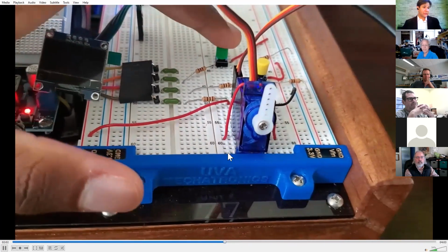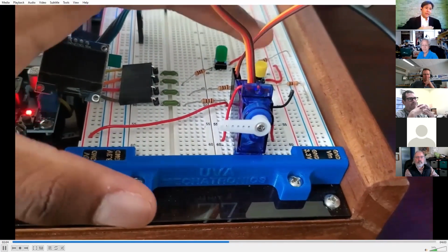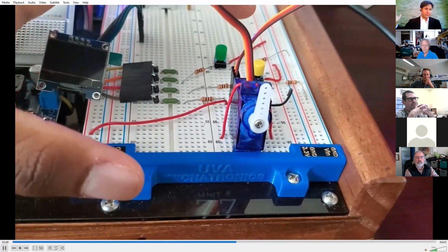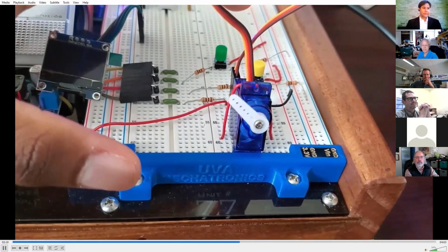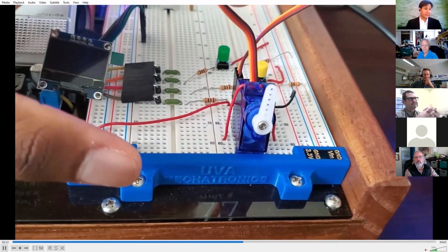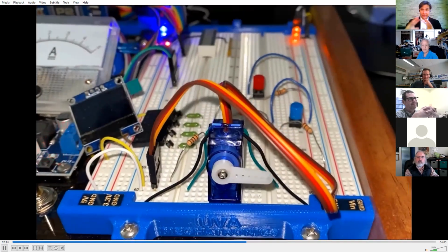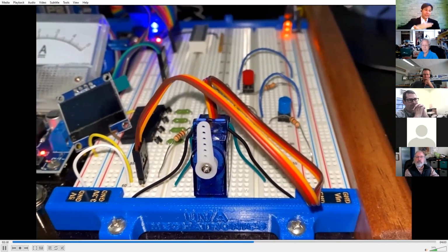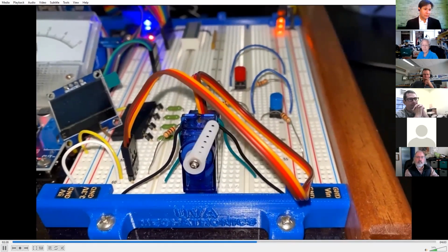They basically have to have a start button that starts the motion. And then they also have to incorporate a kill switch. So if anything goes wrong, somebody gets their hand caught in the machine, it can automatically unwind itself. For this, parallel processing is really nice because rather than having to deal with interrupts, you can just say, if anything bad happens, somebody hits the kill switch, immediately stop it, unwind it, go to the safe position and wait for a restart.